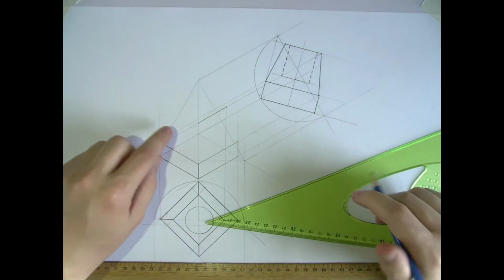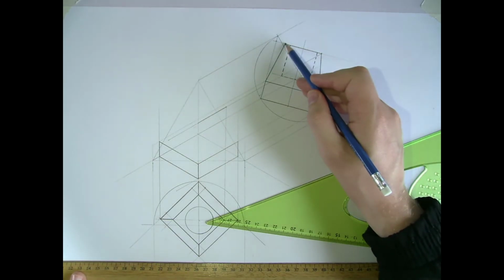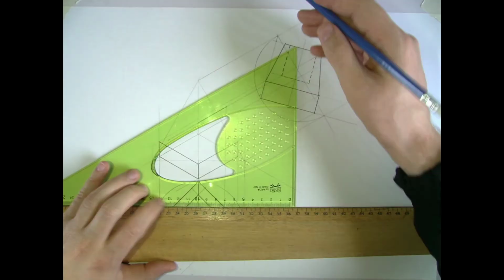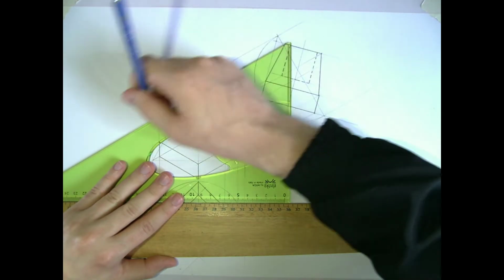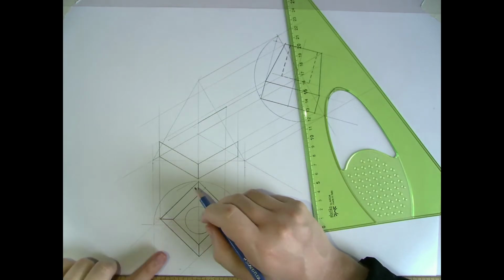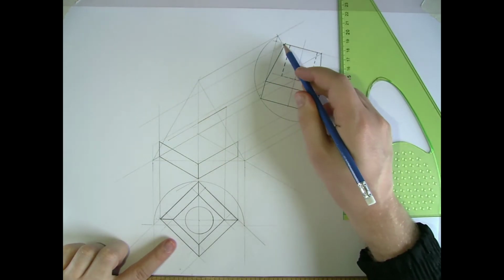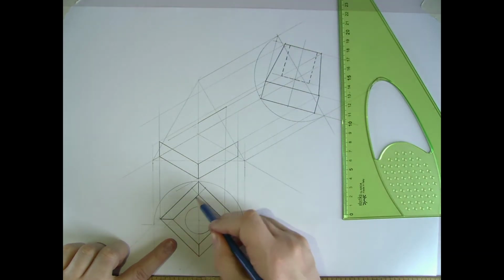Going to have the same coming from the opposite side. So this point, project that one down. That is going to be this one and this one, the corresponding points, because as I said, we're looking at this way at it. So this corner here is an edge view of this line looking back, or point view of this line.